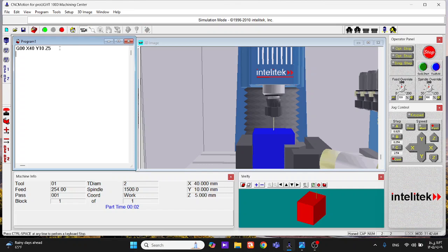So what should we do now? Of course, because the spindle is now turned off, when we want to go to depth and start to make the shape, we need to start our spindle. What was the code for turning on the spindle? It was M03. Now what we should do is define the spindle speed. It can be between 1000 and 5000, but because our specimen is plastic, we will go with 2000. I think it will be enough. It's the speed of the spindle.